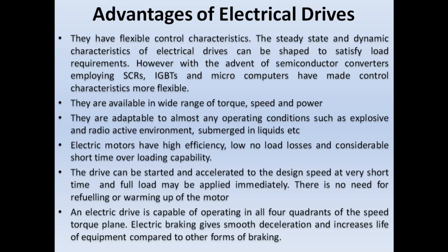If you consider the example of an induction motor drive, you have already studied the torque slip characteristics of an induction motor. By varying the supply voltage or supply frequency, or both supply voltage and frequency, that is the V by F method of speed control, provided at the input side of the induction motor, you will be able to fix the operating point anywhere in the stable region of the torque slip characteristics of the induction motor according to the load requirement.